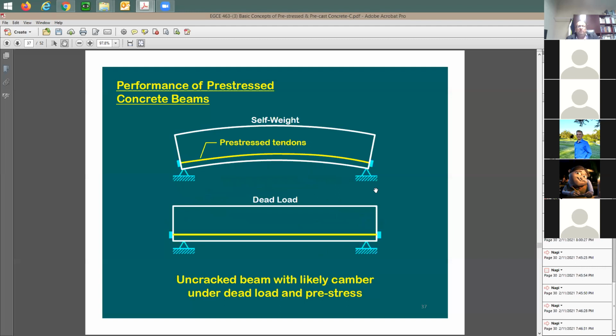In pre-stress, it's completely different. Before you start to apply the load, once you start to put the tension here at the bottom, what's going to happen? You're going to have stresses on the beam. The beam is already stressed. So this is a big difference here.